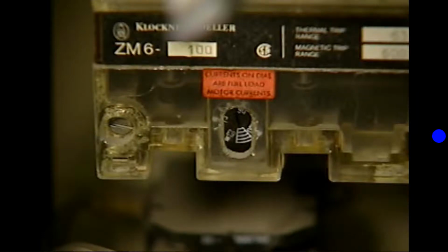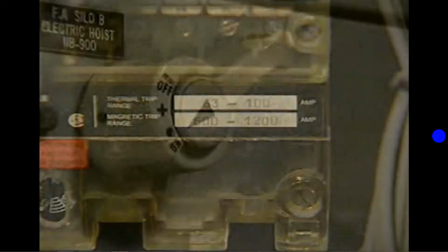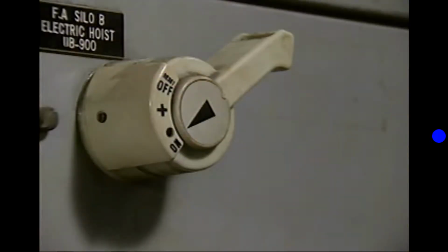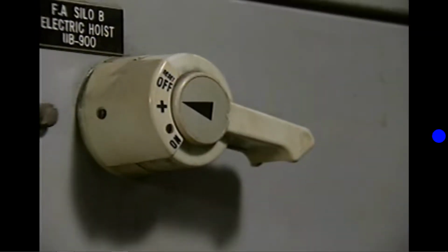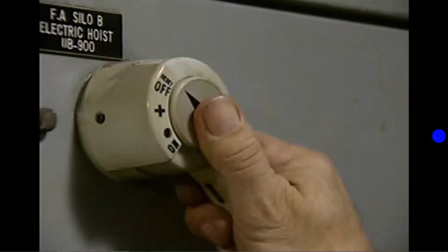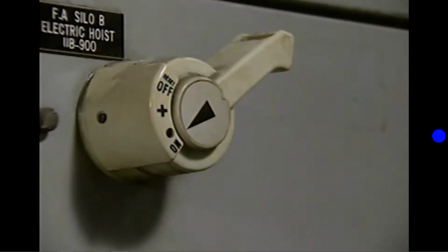The selection or setting of a breaker's trip point is based on the amount of current that the branch circuit is designed to carry. Most circuit breakers that have adjustable trip points have the current values for each setting marked on the breaker case. A circuit breaker works like this. When excessive current flows through, the breaker opens or trips automatically to interrupt the flow of current. This circuit breaker can be reset by moving the breaker handle first to the off or reset position and then to the on position. This procedure resets the circuit breaker and allows the circuit to be re-energized.